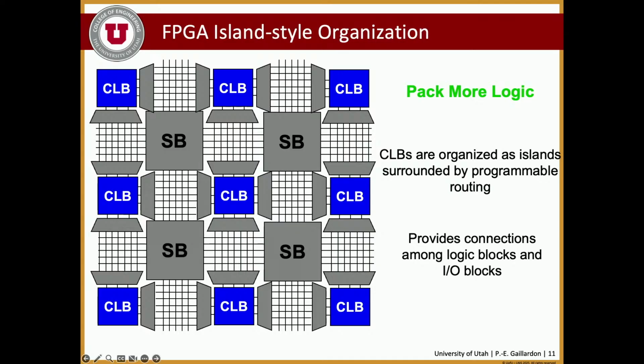But basically, that will provide us with a way to connect logic blocks and I/O blocks or whatever you have on the periphery. Now, here's the trick, right? You should have complete routability of your system, but you cannot guarantee you can make all the routes at all times, right? Every single block can be connected to another block, but not at the same time. So that becomes a placement and routing problem, in order to use the available resources to implement your circuit. So the whole game in terms of the tooling will be to maximize the resource utilization rates without degrading routability and performance, right?